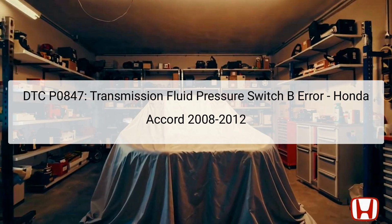Any electrical faults resulting in this DTC must be addressed, as they can lead to transmission performance issues. It is important to note that mechanical issues are not the cause of this code, directing troubleshooting efforts towards electrical diagnostics instead. Operational failures reported through the HDS, or Diagnostic Scan tool, should include freeze frame data, which helps outline the conditions under which the fault occurred, providing critical context for repair.